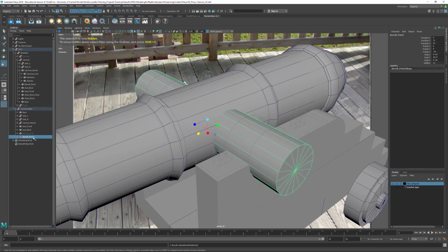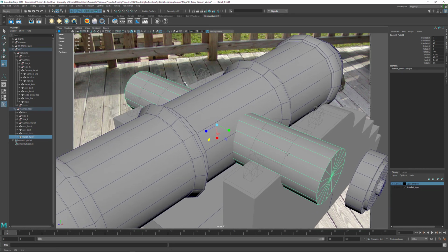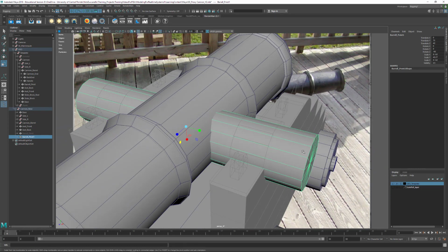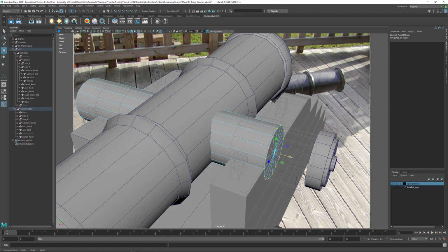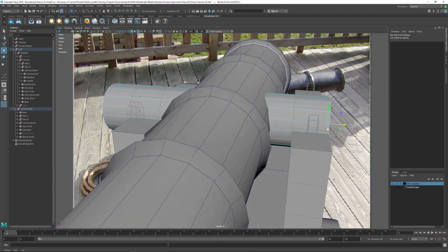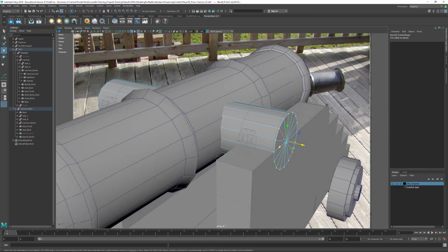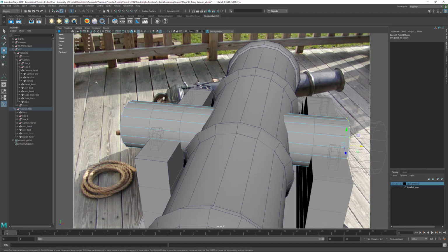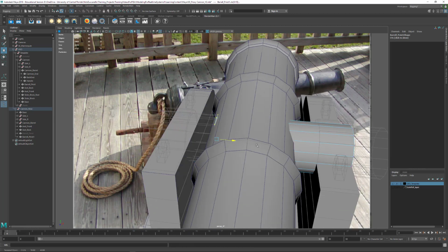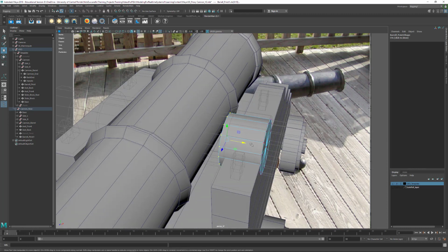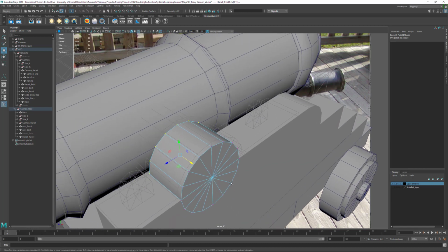So that hides that piece, and now we've got this piece that we're going to be working with. What I can do is take all the verts on here, so I can tap F9, or you can right click on here and say Vertices, either one, doesn't matter. You can tap W and then hold down X and snap in for the grid, or you can hold down V and snap in through here for the edge of that thing, either one. So I think that works for us. The other thing we can do is select all these verts and move them in right here. We could hold down V and then snap to that vertex right there. And that gives us what we see here.